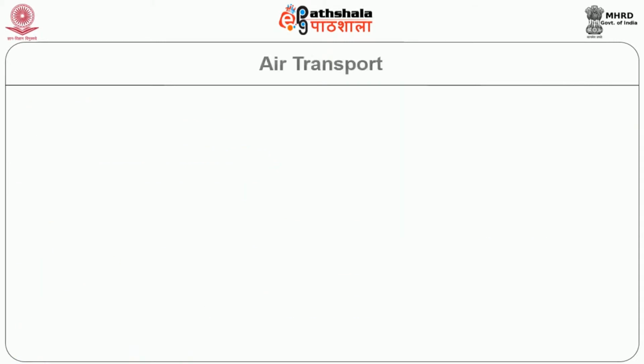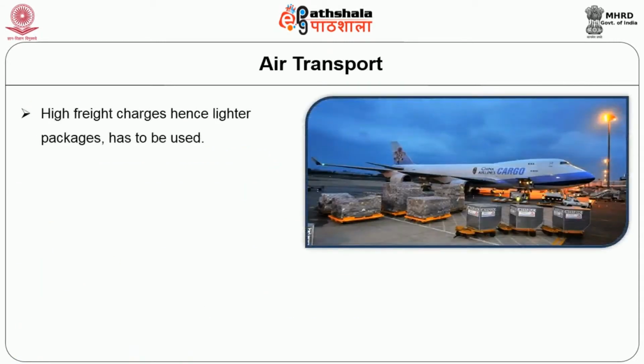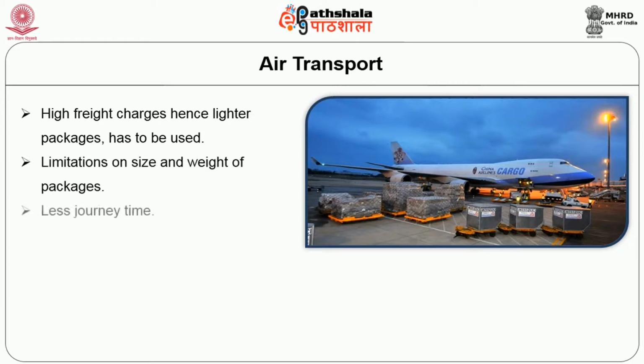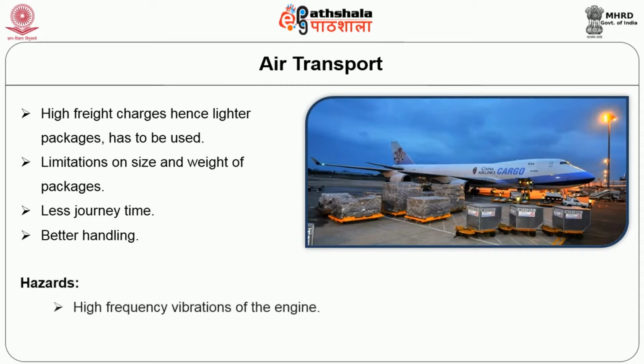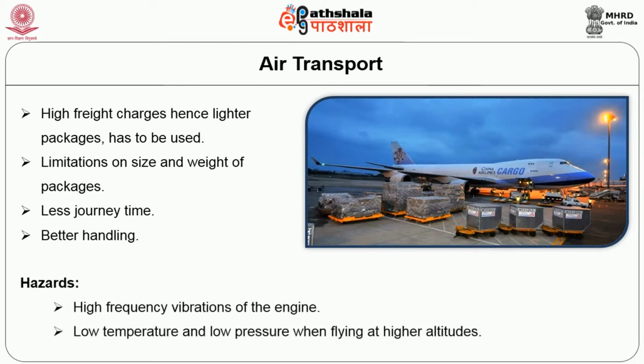The next transport is air transport. High freight charges, hence lighter packages have to be used. Limitation on size and weight of packages, less journey time and better handling. The hazards are high frequency vibration of the engine, low temperature and low pressure when flying at higher altitudes.